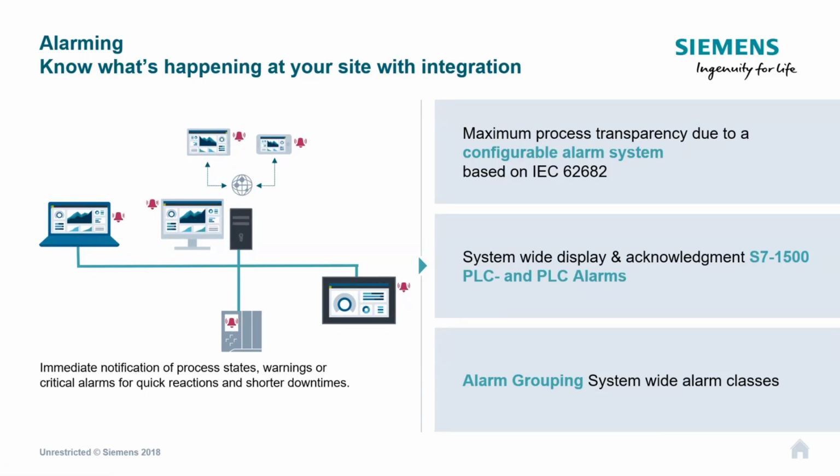It also gives us additional benefits, such as if we were viewing the alarms through the PLC web server and we wanted to acknowledge at that point as well, that would again acknowledge at the controller and push all that acknowledgement out to all of the connected HMIs.